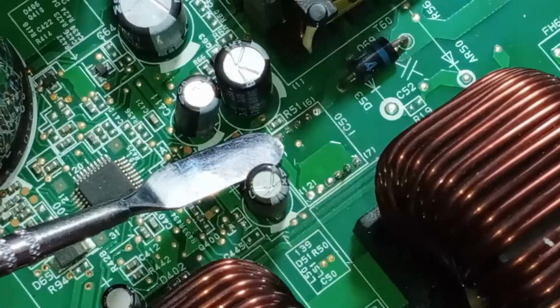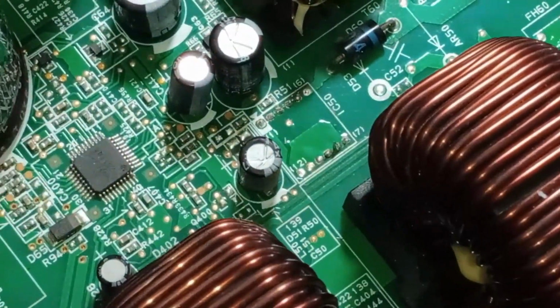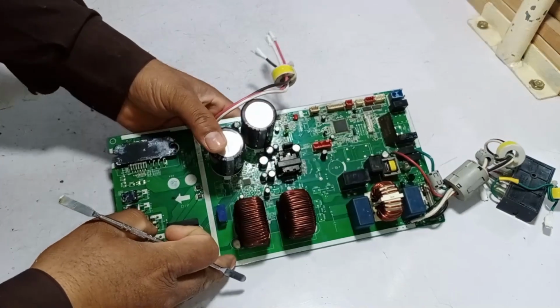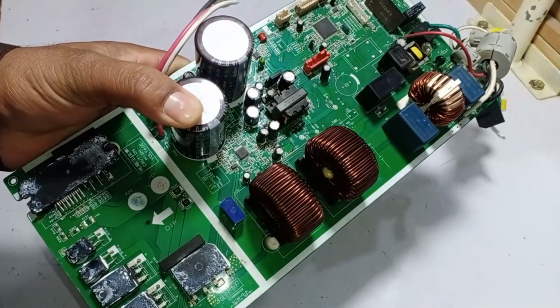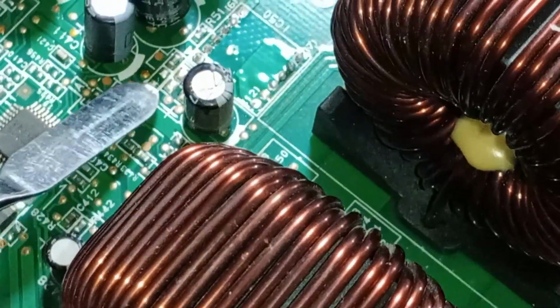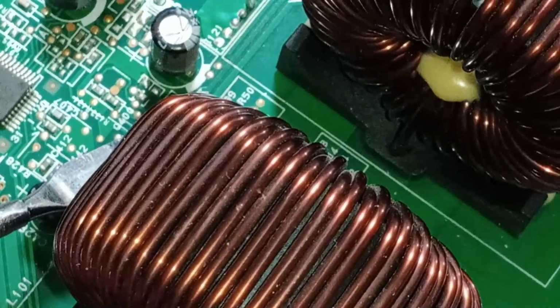As you can see, I have already removed the switching IC from the PCB. The control voltages associated with it, along with its voltage regulator, specifically the Zener diode, have also been found to be faulty. This Zener diode had its number marked on it, which was 51. I have already removed this diode as part of the repair process.